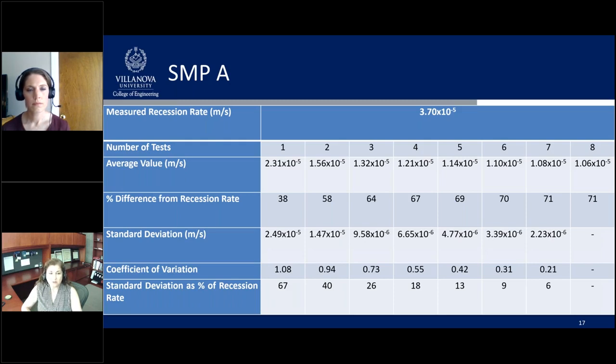The way that this was obtained at this particular site was with a simulated runoff test where we basically got a lot of water from a nearby hydrant and were able to fill up the rain garden very, very quickly and then measure how long it took for that water to recede into the ground.